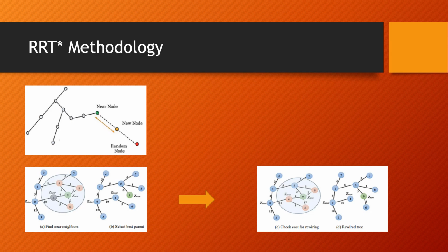As you can see in image 1, this is the RRT star expansion process. The tree expansion in RRT star works by creating multiple short paths, randomly organized as a tree, instead of long paths. It starts at the initial point and finds a path towards the goal. If the random sample lies in the obstacles in the configuration space, it is ignored. If it is in the obstacle-free region, then its nearest node is determined. With the local planner, it connects the nearest and random nodes by a steering function. A Voronoi bias is what drives exploration of the free space, followed by a collision check.